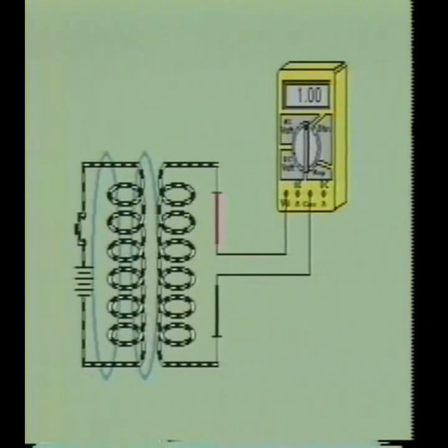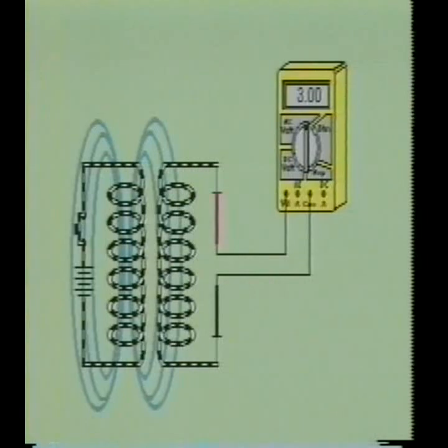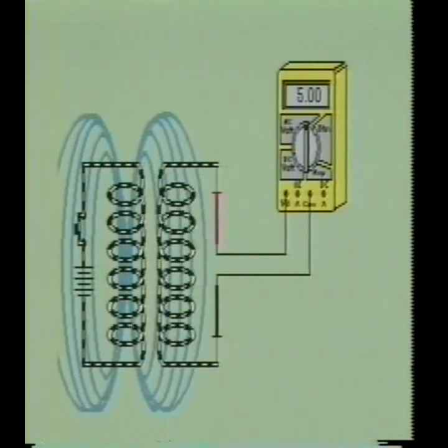This induced voltage will be such that it will be in a direction completely opposite of the direction of the current flow. Because of its opposing direction, it is called a counter-electromotive force. The effect of this counter-electromotive force, which builds up in the conductor, is to oppose any increase in current. At the instant the current begins to flow, the lines of force will be expanding at their greatest rate and the greatest value of counter EMF will be developed.